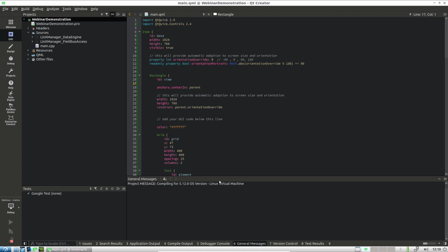While it's doing that, I can give you a heads up on what we are going to do now. Firstly, we need to create a virtual CAN network since we are running this presentation within the virtual machine. Secondly, I'm going to replay CAN traffic because I don't have a CAN dongle attached. We need to have the data taken from somewhere, and that's going to be a CAN trace file.